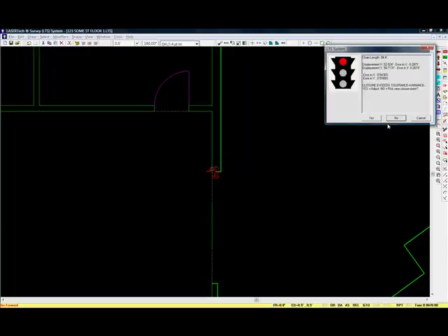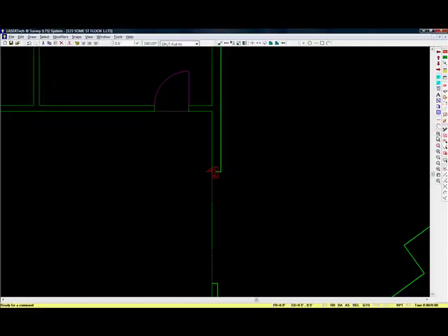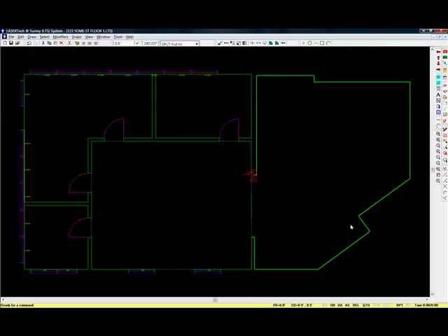angles like that. And we do our check, and we find that we're out 0.28 feet in both X and Y. So there probably is a little bit of an error there, and I'm just making these numbers up, of course, but in reality if we had distoed it and triangulated properly we'd be closer than that. If not, you'd have to go back and check. Seeing as the error was about the same in both directions, I suspect it's probably the length of this line here. Maybe we disto it again and we find it's 9.9.